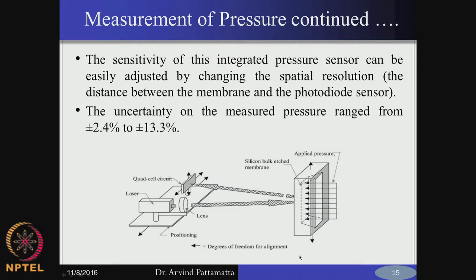The optical lever method is a more expensive technique. You need a laser mechanism, which will illuminate the laser onto a flexible membrane made of silicon. This silicon membrane is connected to the pressure tappings on a micro channel. Depending on the deflection of this membrane, the reflected intensity of laser will have different angles. The deflection angles will be a function of the deflection of the membrane.